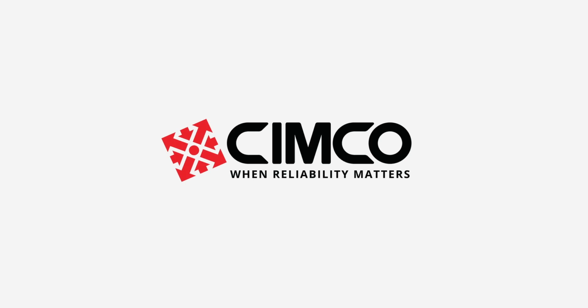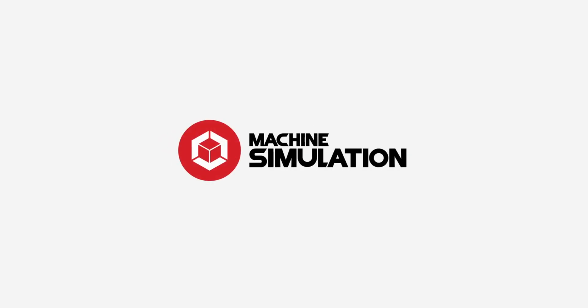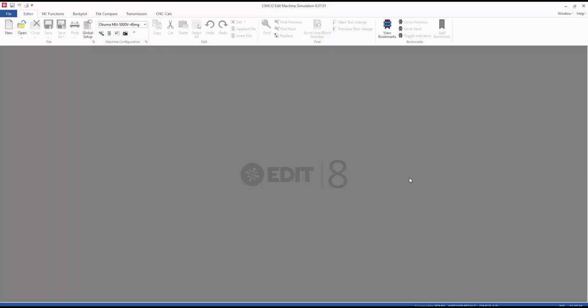The following video will demonstrate the Machine Configuration Editor feature. The Machine Configuration Editor allows users to create and define machine configurations. Users can add geometry to an individual machine component and also determine the axis components of the machine, the travel limits, feed rates, and the tool change position.